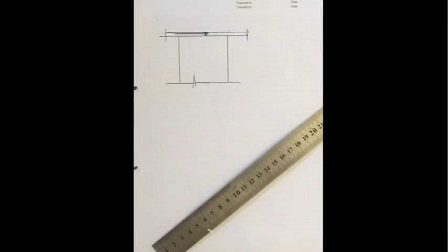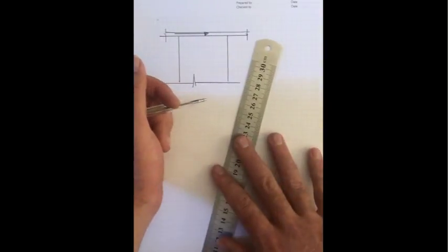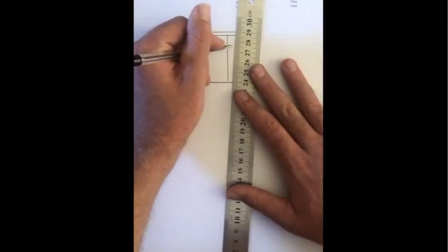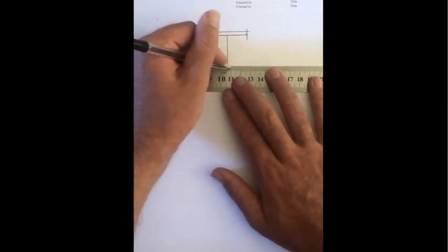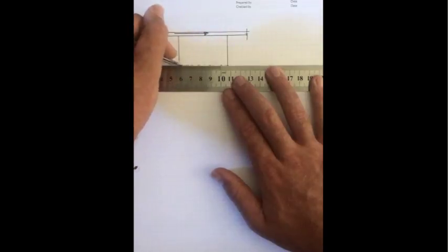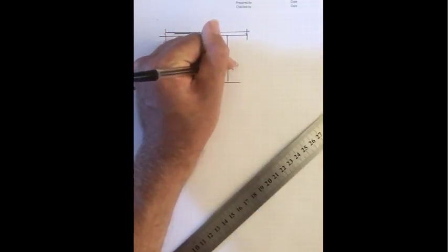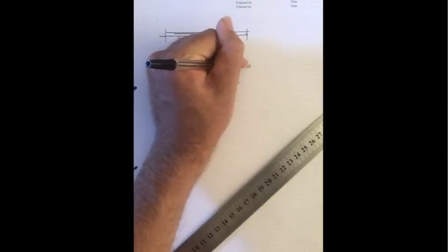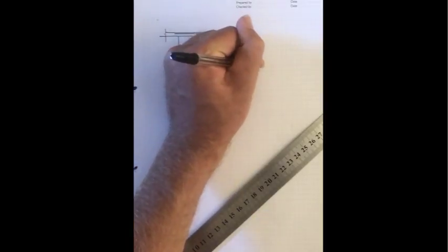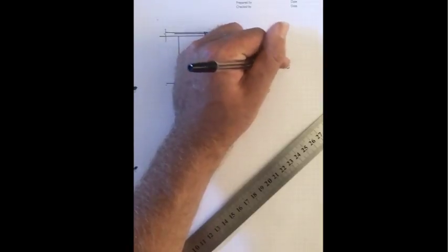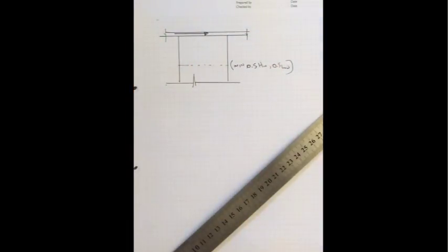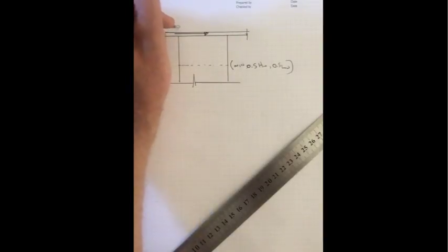First of all, 11.6.1 says the critical section for shear is either 0.5 times the length of the wall or 0.5 times the height of the wall, whichever is less. So we'll be taking the shear strength at maybe this point here, and this is the min of 0.5 height of the wall or 0.5 length of the wall. But either way, we'll get in to find the strength. Say we've got a 500 kilonewton load here, which is significant, perhaps from stability.